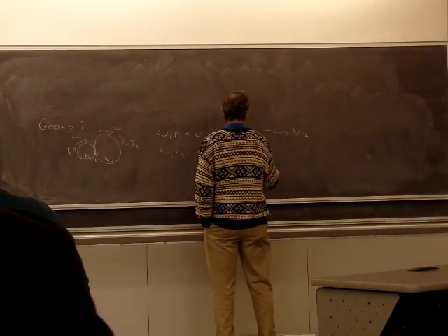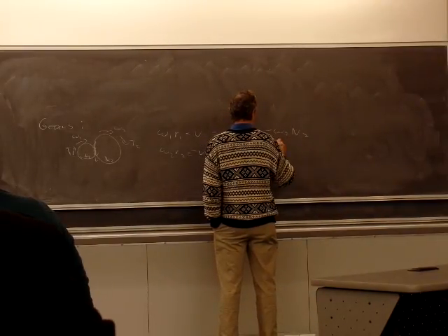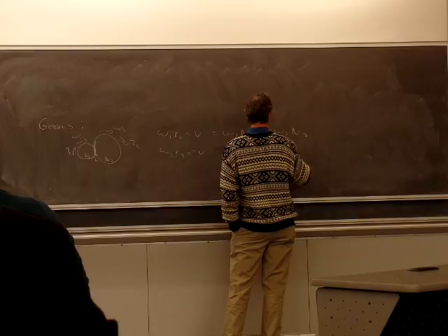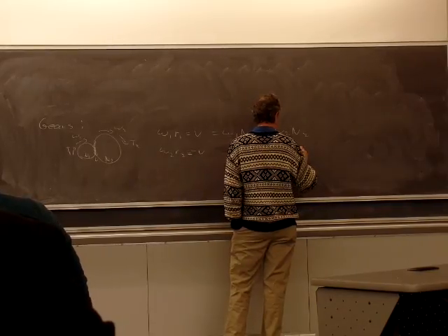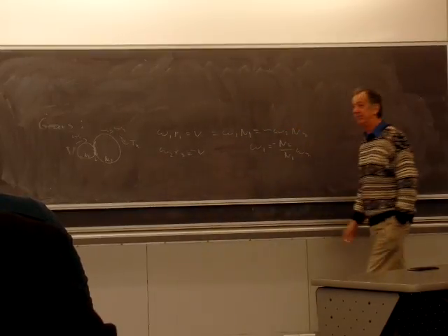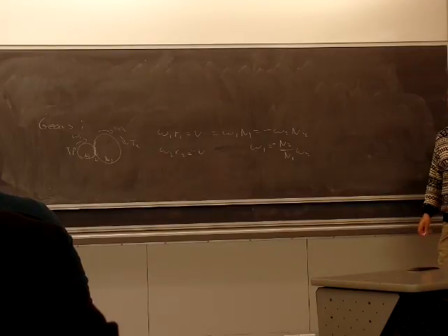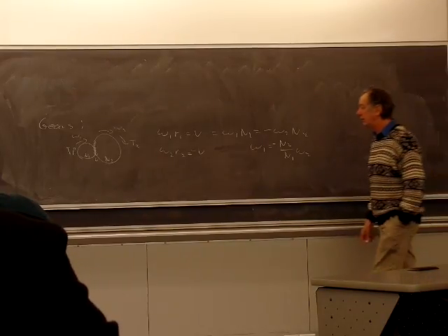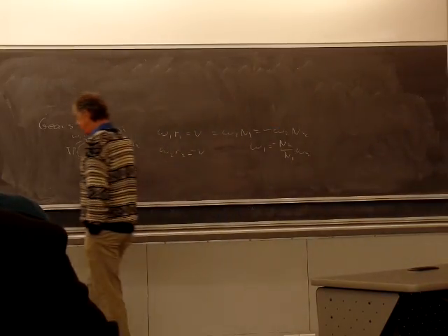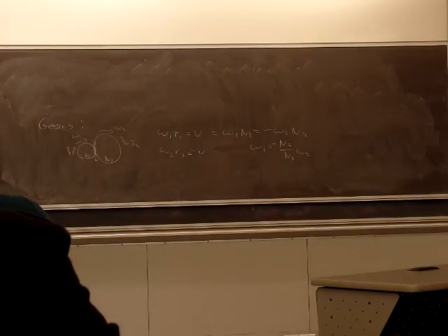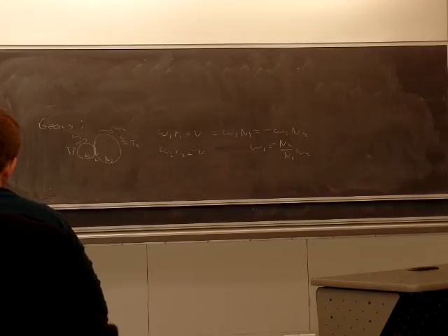So, the relationship: minus, this one. It's negative because it's directly reversing direction. Okay, let's look at torques. What do we know about the teeth in terms of the torque? The force of one tooth onto the other tooth must be equal to the other tooth's force acting on this.